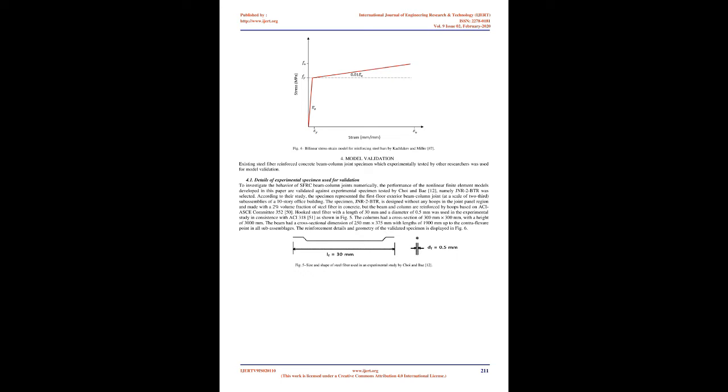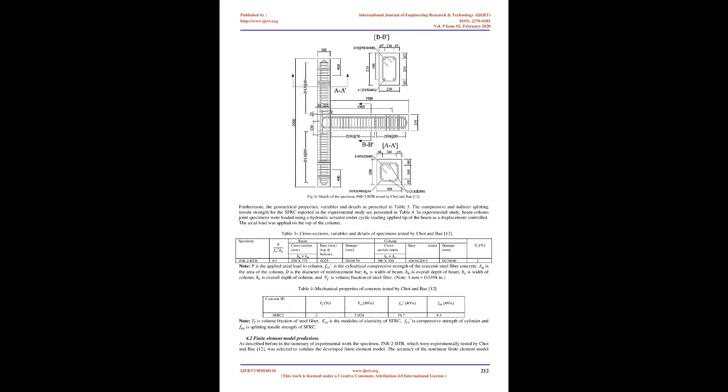3.5.1 Modeling of SFRC in compression. Several investigators have proposed models for the characterization of the compressive stress-strain behavior of SFRC [26-31]. All have relatively similar approximations of the SFRC behavior under uniaxial compression. Generally, steel fibers only have minor effects on the ultimate compressive strength of concrete, slightly increasing or decreasing its magnitude, depending on the characteristics of the fibers [25-32]. However, the use of steel fiber in concrete significantly enhances the descending branch of the compressive stress-strain curve.